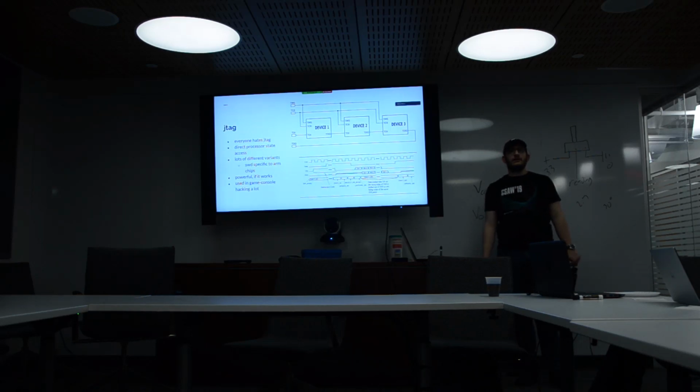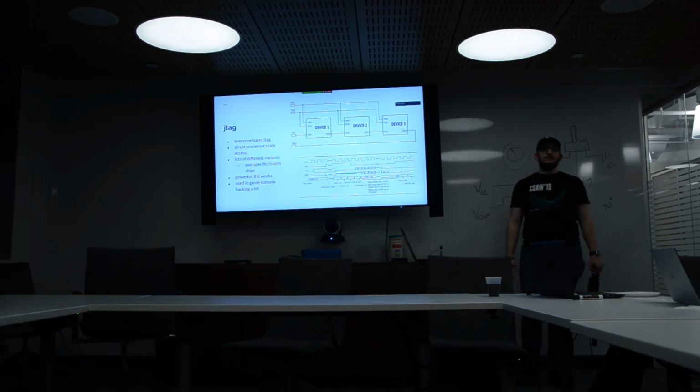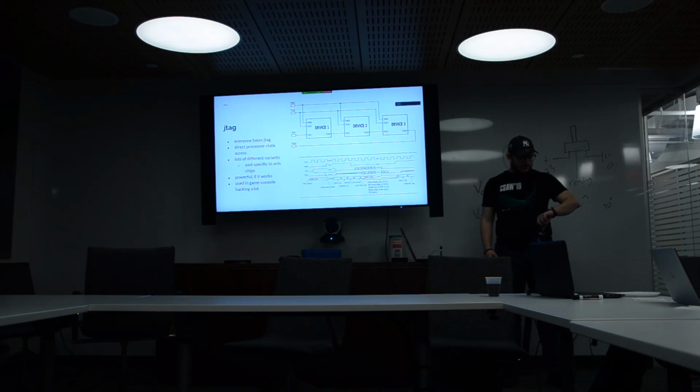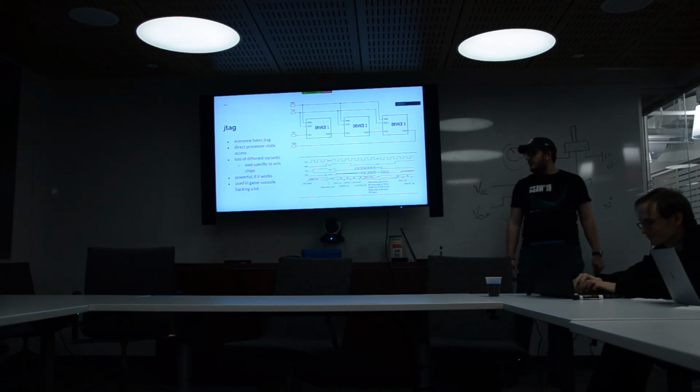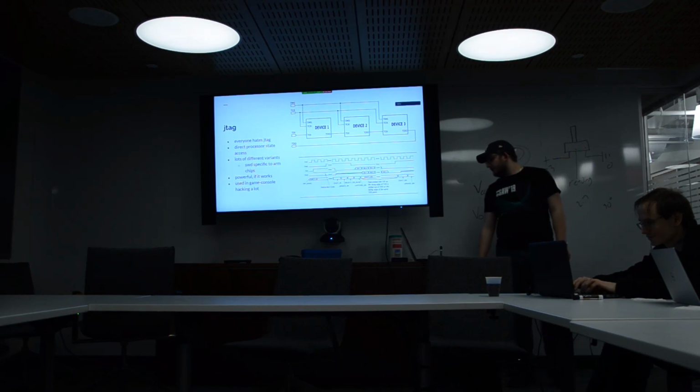It gives you, I think, ring -1 access technically, because you can actually view processor internals, which is not something that you get super regularly. There are a lot of different variants. You have something called single wire debug, which is specific to ARM devices. That gives you full processor inspection, so that's really cool. JTAG is super powerful if you can get it to work properly.